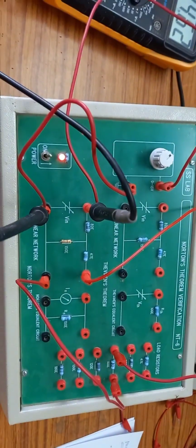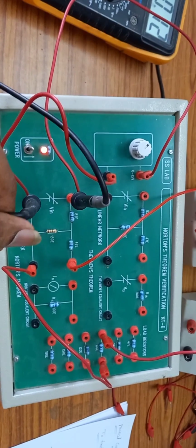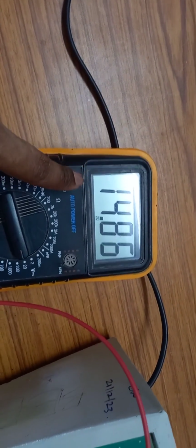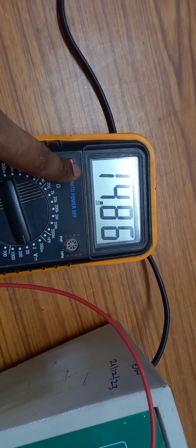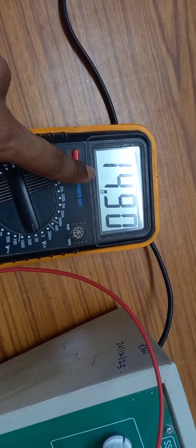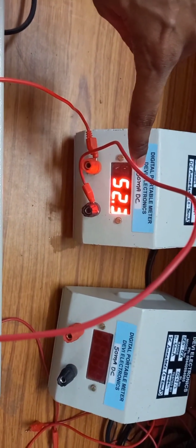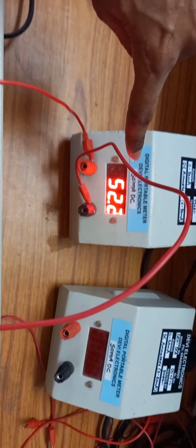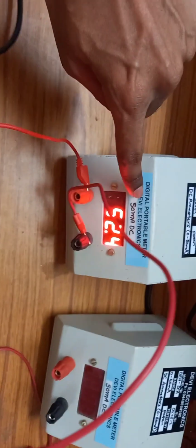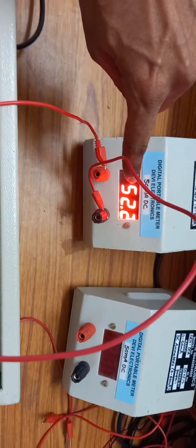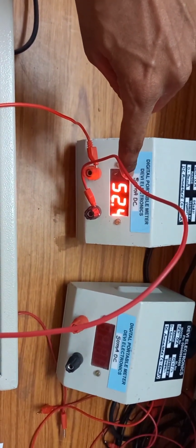Okay, you remember here I have connected one multimeter at the input place. So you observe in the multimeter 15 volts. Okay, it's varying a little bit. You don't worry about that. 15 volts I have taken as power supply. Then you observe in the ammeter we got 52.3 into 10 to the power of minus 3. It means this is a milliammeter, no? So that's why we need to take 52.2 into 10 to the power of minus 3.